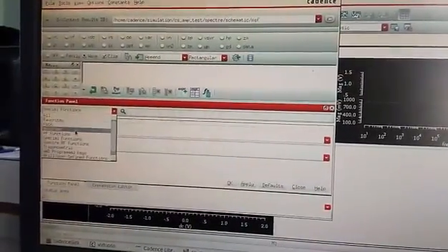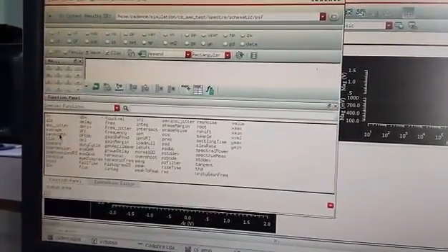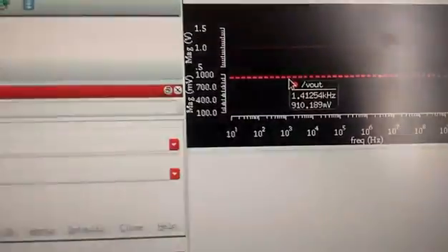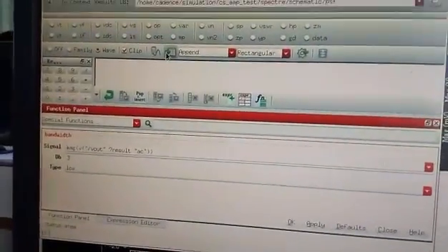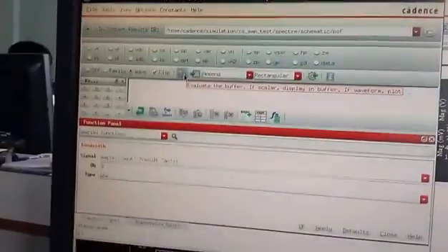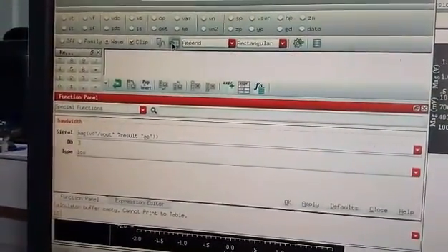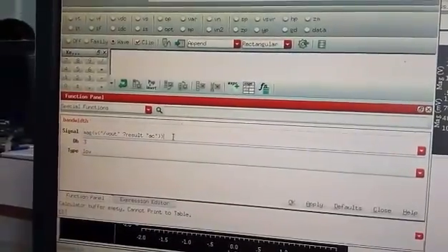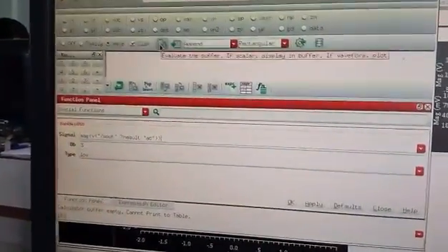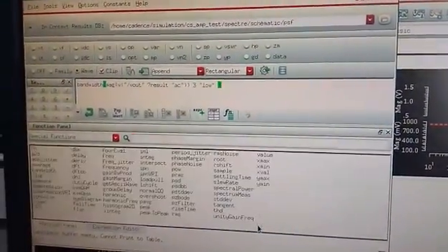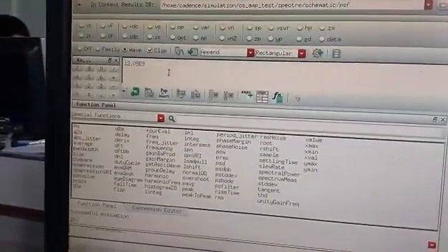Now what you do is select on special function, bandwidth here for example, signal, and remove whatever is extra. Now select on the line obtained. The table gives you the output, I mean the action, whatever's going on from one frequency to another. Let's click on apply. Okay, there we go. Now run. Yeah, there we got the bandwidth.